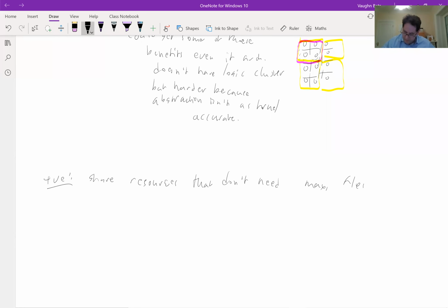So they don't need the maximum flexibility. Okay, so essentially we can make some word wide. We think of the logic block as now our word, we can make them word wide signals. And so a good example is clocks. I might have lots of clocks in my design, but if I have 20 registers in my logic block, I probably don't need 20 different clocks coming into the logic block.